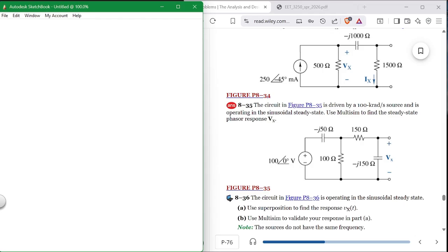How would you do this one? Well, there's about half a dozen ways you can do this. One would be to write a voltage VB right here, which still doesn't give you the final answer, but it gets you close. It gets you the voltage here, and then you can use a voltage divider to get the final voltage.